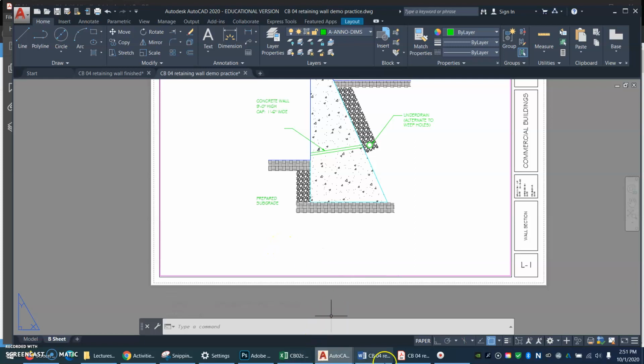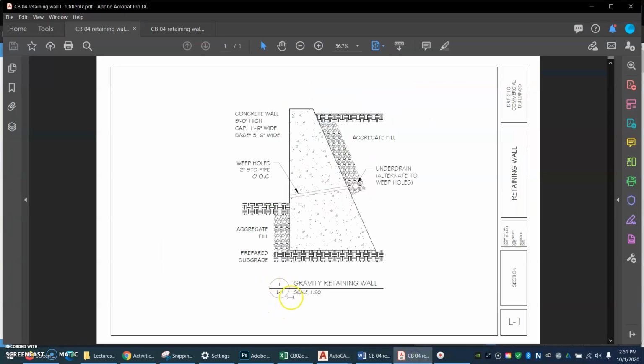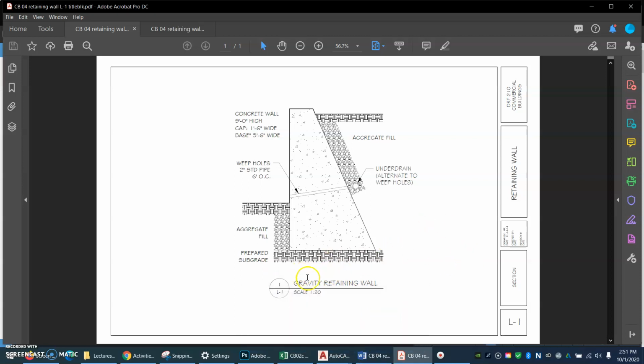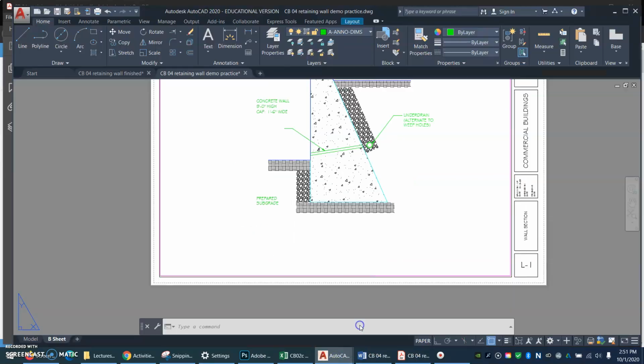the circle thing, is supposed to be 5/8 of an inch in diameter with 1/4 inch title text and then 1/8 inch other text. Okay, so let's go. I like to start with that circle. I'll show you why. So I'm going to make the circle center point.